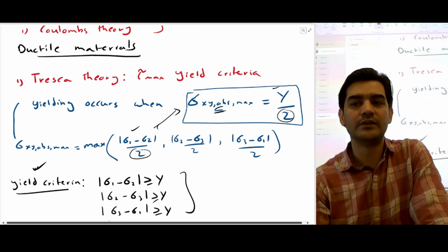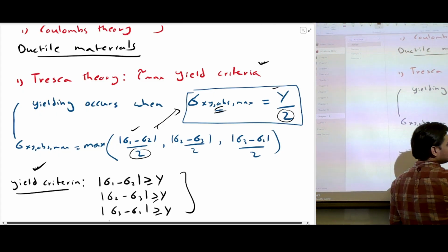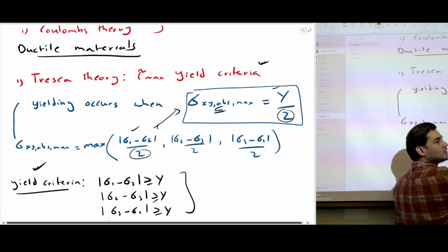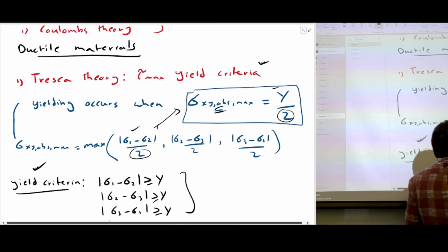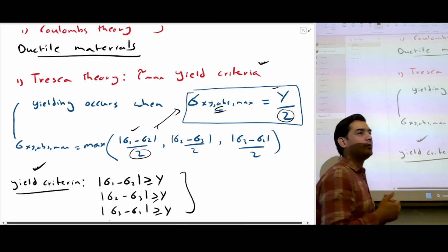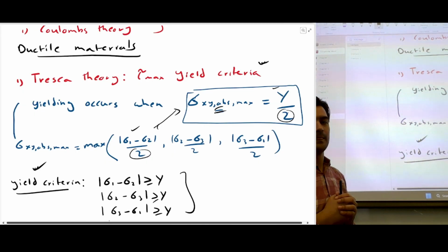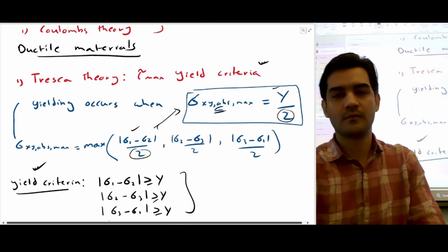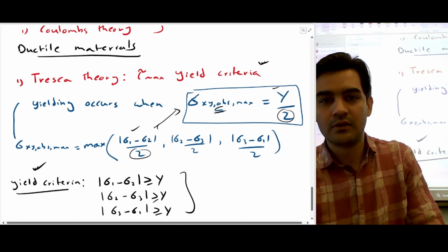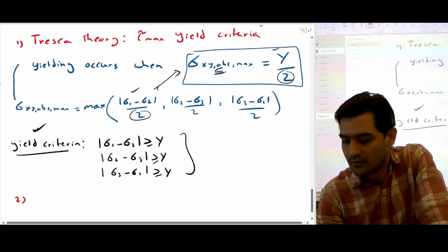So that's Tresca theory. So Tresca theory says calculate the maximum principal stresses, subtract them, and see if the combined stress you're getting from the stress element is higher than the yield stress or not. If it's higher, then it's a failure. Then we will observe yielding in a given stress environment. So that's what is called Tresca theory. Now the another one is von Mises.